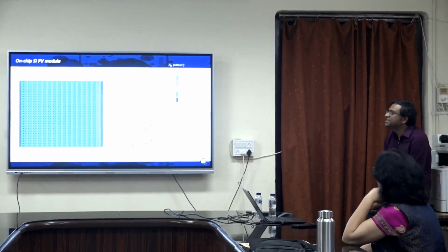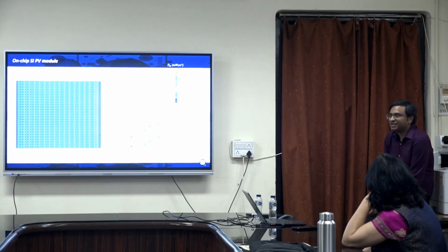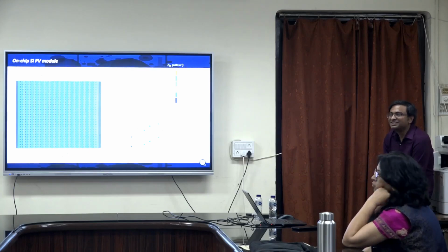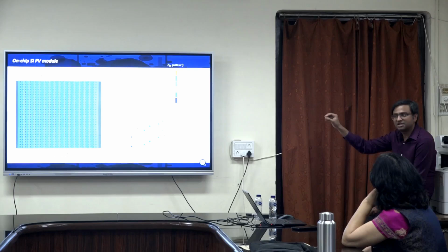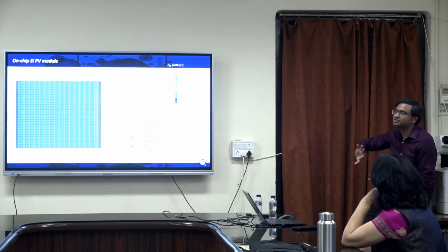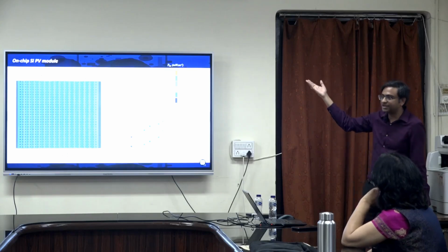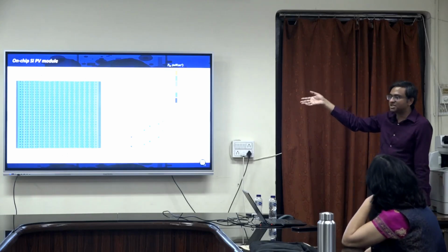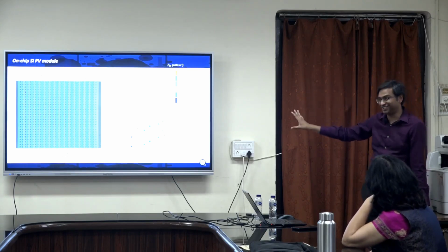Yeah, because the efficiency of these cells that we have made, I do not even want to tell it. It is very shameful for me to tell that number. The number is only close to 0.1 to 0.5 percent. This is the concept, yes. So right now the efficiency of these solar cells is very poor, because what we are using is just a Schottky barrier solar cell. And the solar cell community has really evolved. Today people use perovskite material for getting to 25% efficiency. Our efficiency is right now 100x lower. It is barely getting to 0.2%.